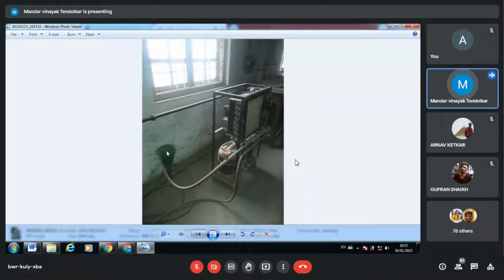And over here, I will hold some measuring flask, 1 liter. One student will take the time reading with the stopwatch. So this way I can measure m dot. 1 kg or 1 liter, one and the same for water, correct? Density is 1000. So 1 liter or 1 kg, and how much time to get it collected. So this is how I calculate m dot.